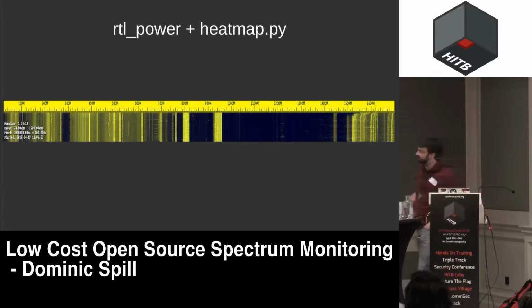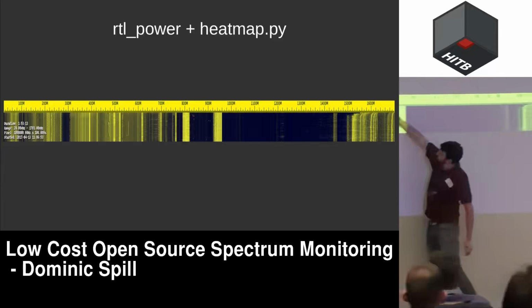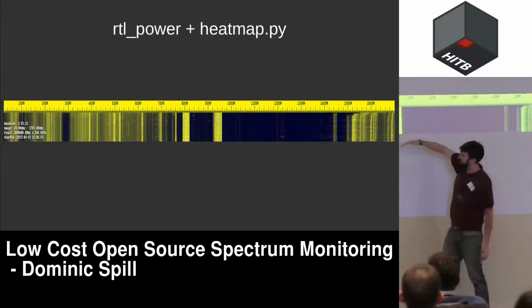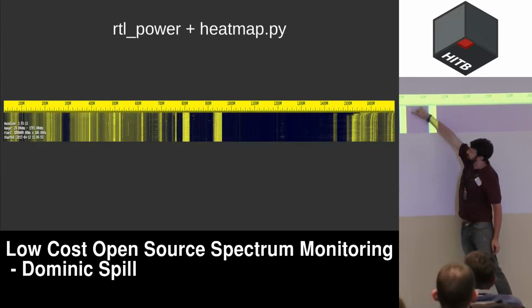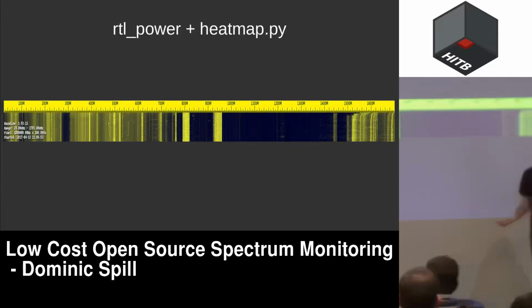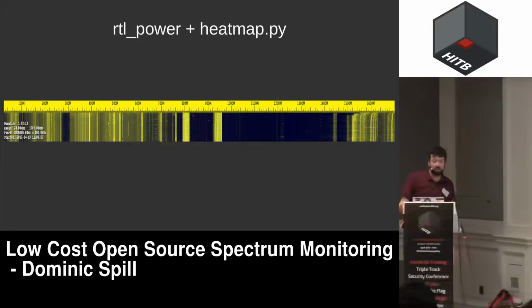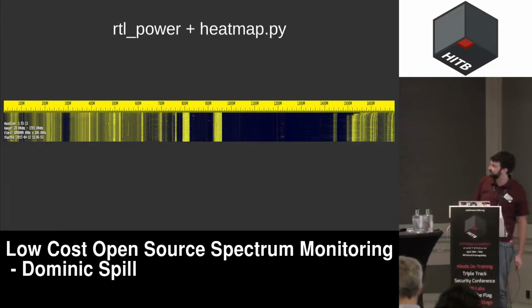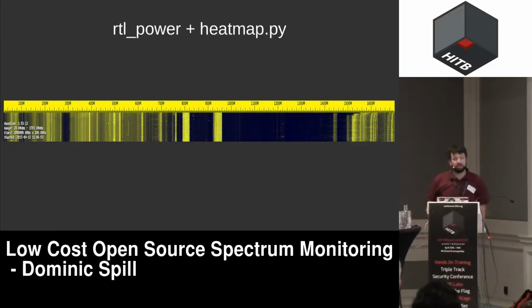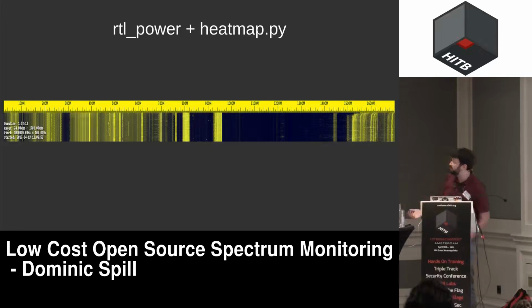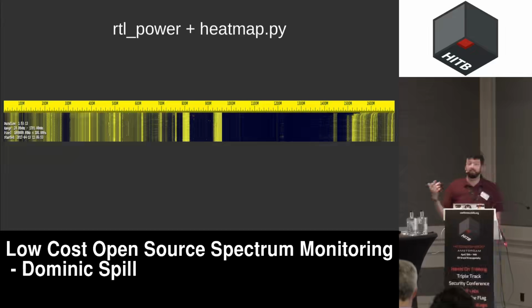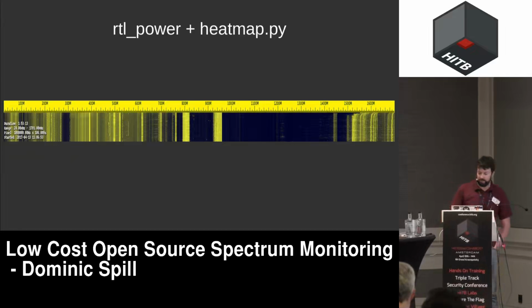But you can also see, and again I'll try and show you, up here we've got some very, very short, to be clear, it's frequency on the x-axis, time on the y-axis. We've got some very, very short transmissions here, and here, and here. So they're much more likely to be, especially around 900 megahertz, unlicensed things. 900 megahertz unlicensed things shouldn't be being used in Europe, but in the same frequency band. But they are likely to be small devices. There's a fair chance from this that I could tell when the hotel staff came into my room to clean it, especially if I were able to get up to 2.4 gigahertz, I'd probably spot their phone and things like that when they entered the room.